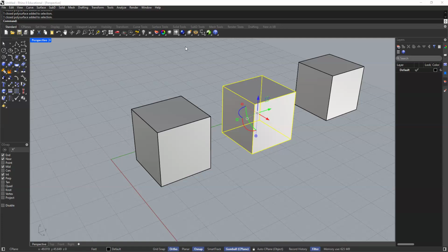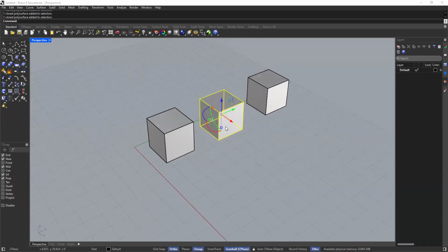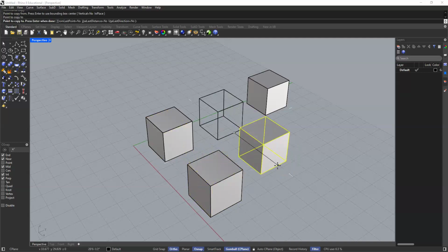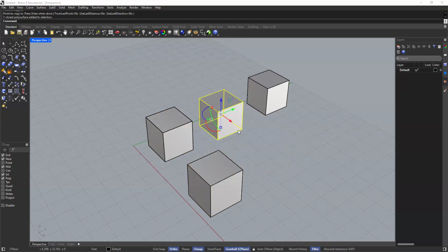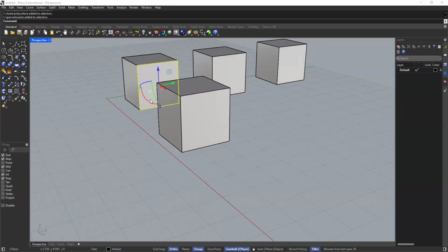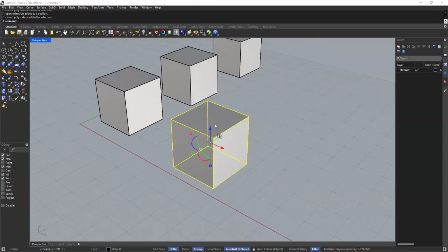Okay. I'm going to take this polysurface and I'm going to copy it over here. You say, well, okay, what if it's a polysurface, but now I want to turn it back into a surface? That's when we use the command explode. It's a bit dramatic of a term, but we're going to use it.